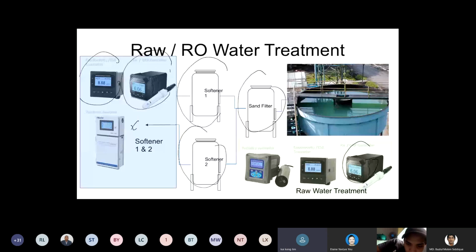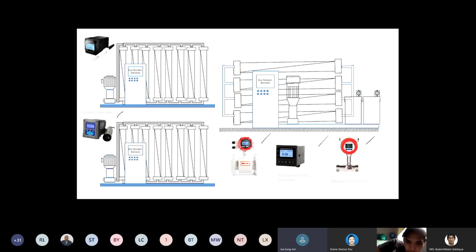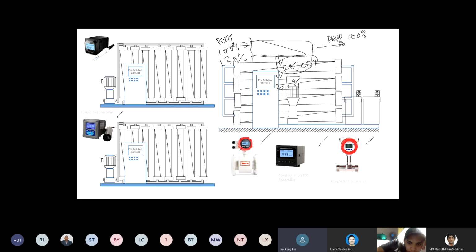The detail, okay, you look at it, this is the RO system here. So in the RO system, we are having a membrane, okay? There is certain parameter we need to control for the brine, or what we call the reject, okay? So the feed water, I'm putting 100% of inlet. Now, the outlet is 100%. Because of high TDS, you actually can't run at normal situation. Normal situation, our reject, some people control at 30%, meaning that the feed is about 130%.